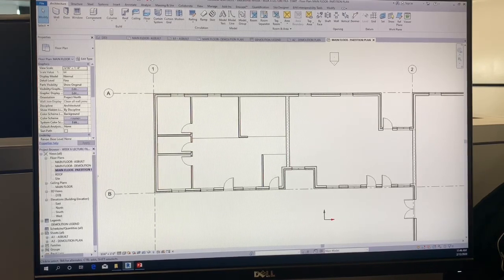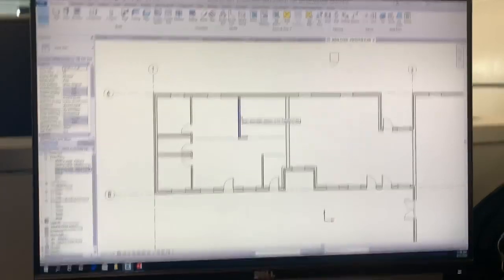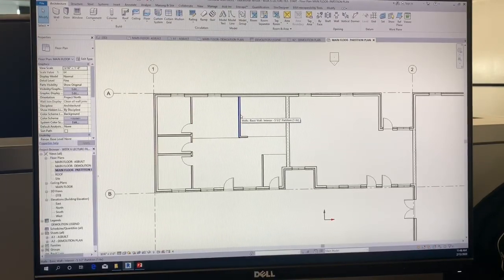Because the last thing I want to see is the wall construction items, or what construction this wall is, on a leader. I never want to see all of this information on a leader placed in the drawing. So what we do is we tag it, and then we create either a legend or a schedule that we place all the information on. So the first thing is we need to tag it.